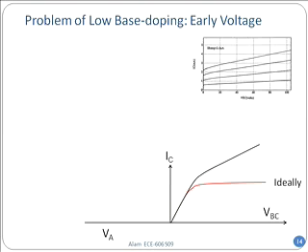Let's say you're trying to listen to rock and roll or something, big, humongous sounding music. I don't think you hear rock and roll anymore, but let's assume that you hear it. Now, if the music is very low, then you have a certain gain. And if the music is very high, or amplitude is very high, then all of a sudden, you should have a proportional rise in gain. If you don't have a proportional rise in gain, anytime the input is small, then you have a certain gain, let's say a factor of 100. Anytime the input is a little higher, if you don't have 100, then the dynamic range from the inside will be distorted on the outside.